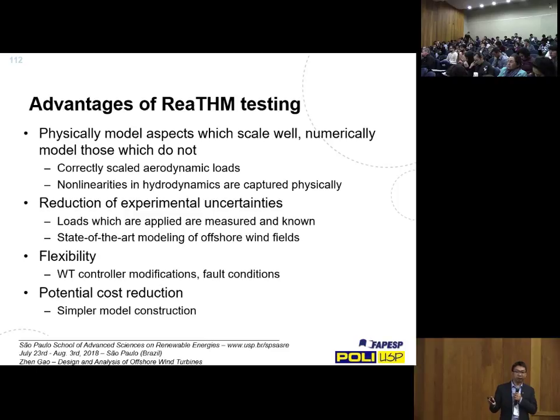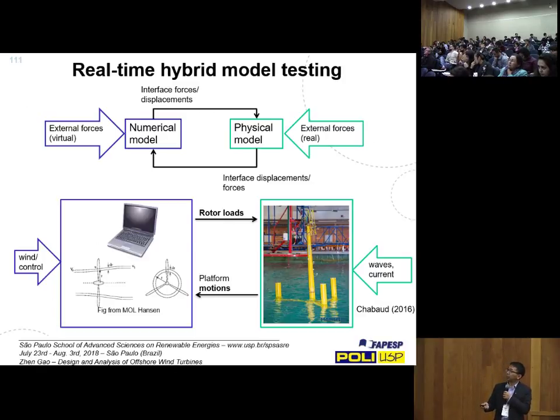But you are free to do this at a numerical scale, so that you can impose these loads numerically and then apply them on the physical structure when you're doing the model test. I forgot to mention that, of course, the test is carried out at a model scale, but these loads are estimated at the full scale and then downscaled by fluid scaling law, so that you apply the model scale value in the model test. And then, of course, you have to do this in real time so that it evolves with the same time to have the coupling effect.